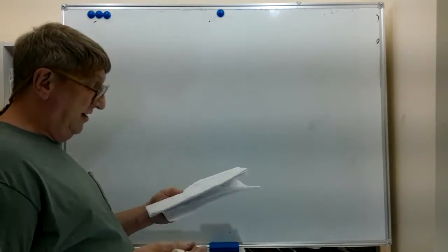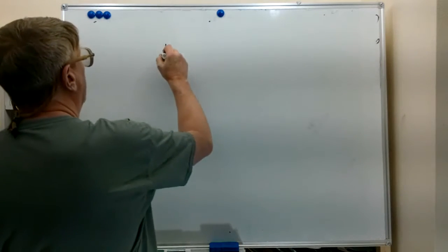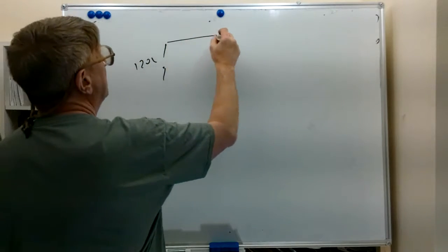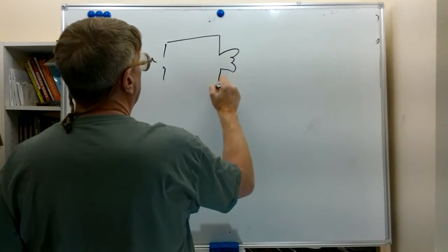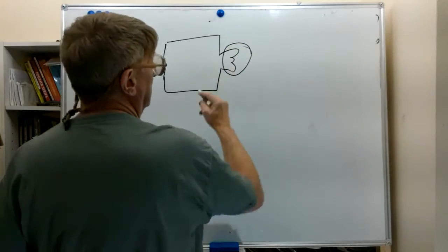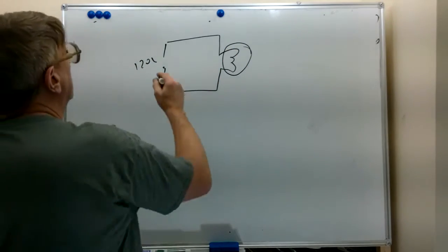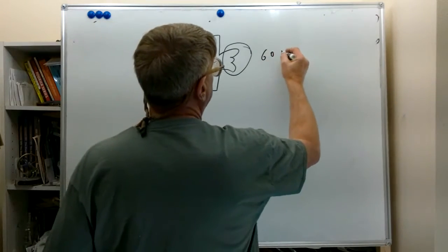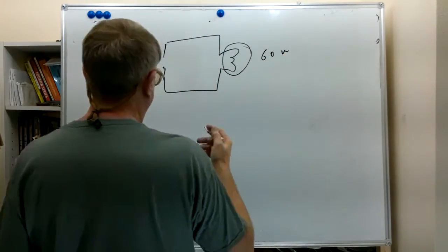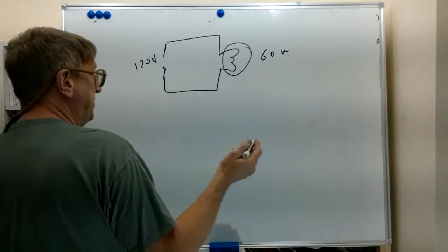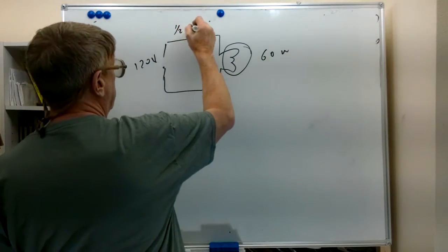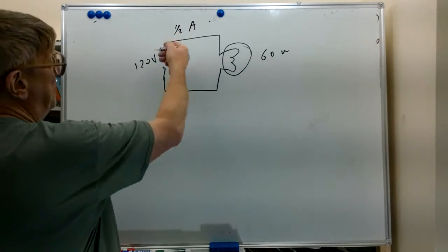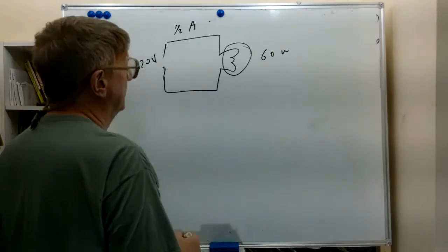It's actually desired. In the case of a light bulb, we'll draw a little light bulb here. We'll put 120 volts on it. We won't worry about the value of it. The symbol for a light bulb, a little globe with a filament in there. I will say this is a 60 watt light bulb. And at 60 watts, we basically have half of an amp flowing here. Power equals volts times amps, 1/2 times 120, 60 watts.